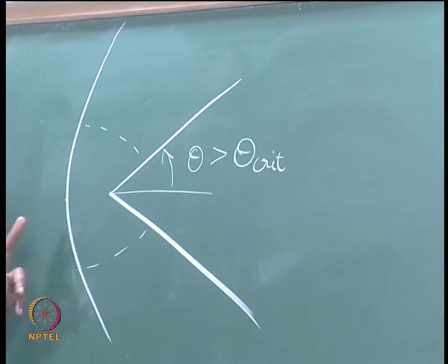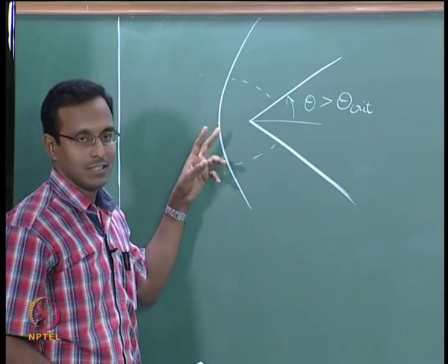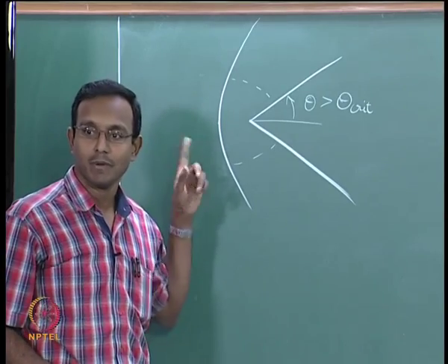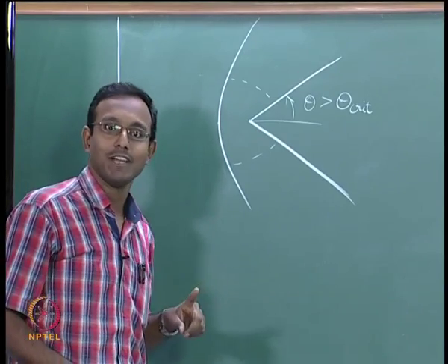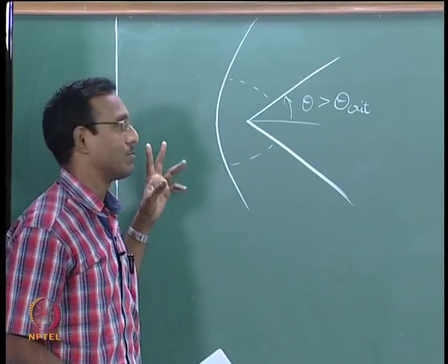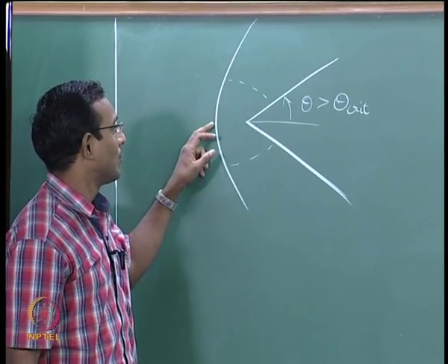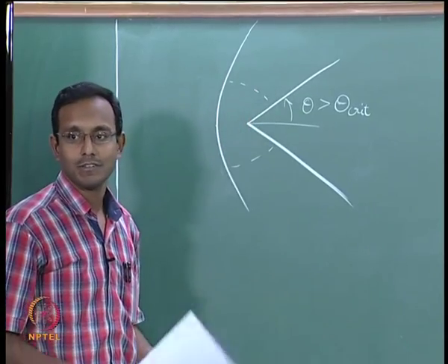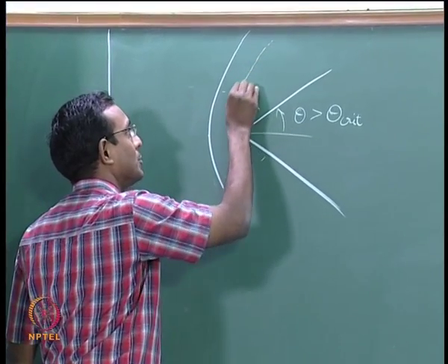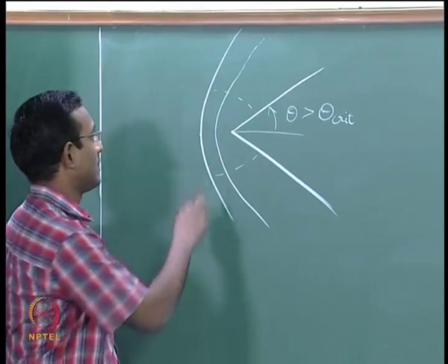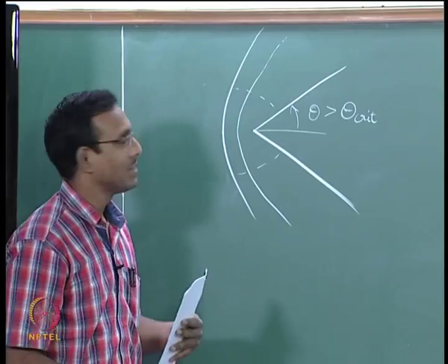And then we said if the gas becomes more compressible, I gave an example of gamma less than the previous gamma. If gamma decreases, then I said it is roughly more compressible. That is not the only way to make it more compressible, that is one of the ways. If I decrease my gamma, the flow has a possibility of having an attached shock. There is also a possibility of it just decreasing to some other bow shock where the standoff distance has now decreased. That also is a possibility. This is something I did not tell last time.